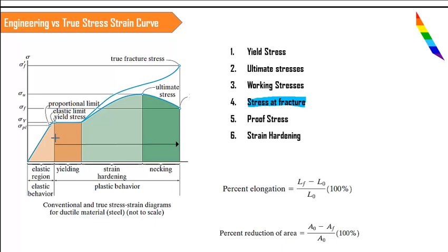In our engineering studies, that means in the mechanics of solids, our entire discussion will be within the elastic limit. We are not discussing anything beyond the elastic limit, because linear behavior is not available in the plastic zone. Linear behavior is only available up to the elastic limit, so we will limit our discussion to this elastic limit. If you want to study something in the plastic zone, we have to go for higher mathematical operators and differential equations, because the conventional linear system of equations cannot be used over here.